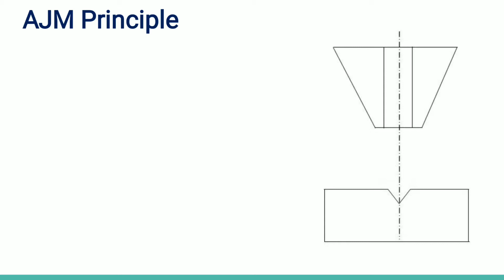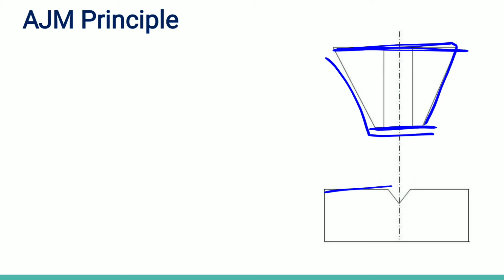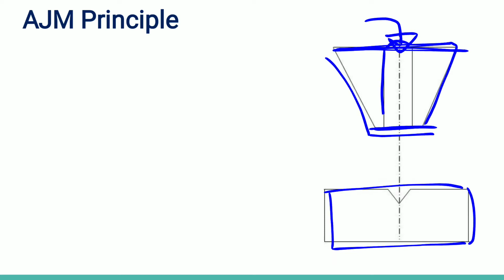I'm using this figure to tell you about the principle. This is basically the nozzle. This is the cross section at the entry point and this is at the exit point. This is a workpiece at the initial level. Now from this side the abrasive particles are coming with a very high velocity. This is a cylindrical portion, a hollow cylinder inside the nozzle.